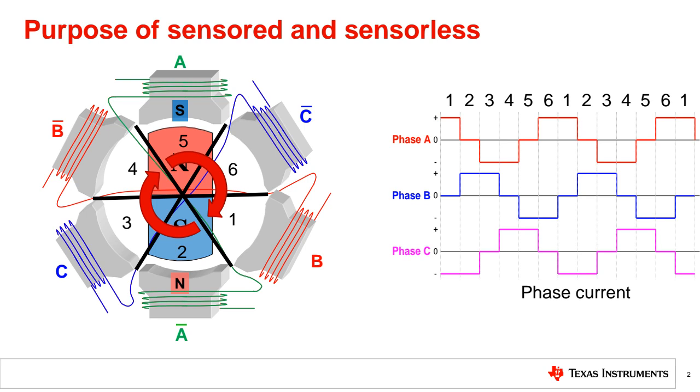However, don't forget, brushless DC and permanent magnet synchronous machine are the same topology. We are using the two of them for different applications. However, we have drive technology for some purposes. Sometimes we are using sensor, sometimes we are using sensorless operation. These are control methodologies.